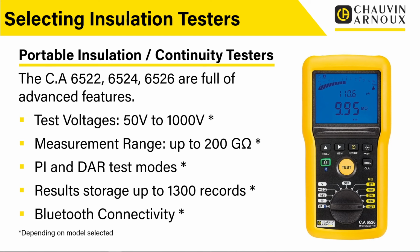So if you're not quite sure, always have a look at the data sheet and you'll be able to pick out exactly which features you want. Within this range of products, we've got test voltages from 50 volts all the way up to 1000 volts, and they're selectable using the rotary knob, as you can see from the image there. Again, measurements up to, in this case, 200 gigaohms. So again, we're talking really high measurement range on these products.